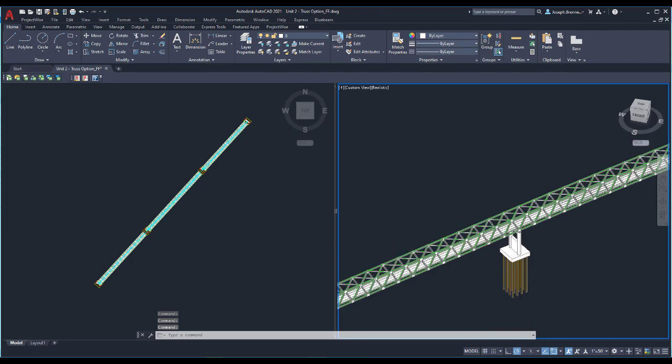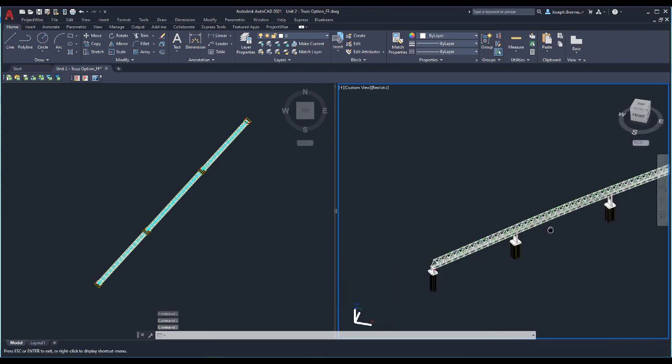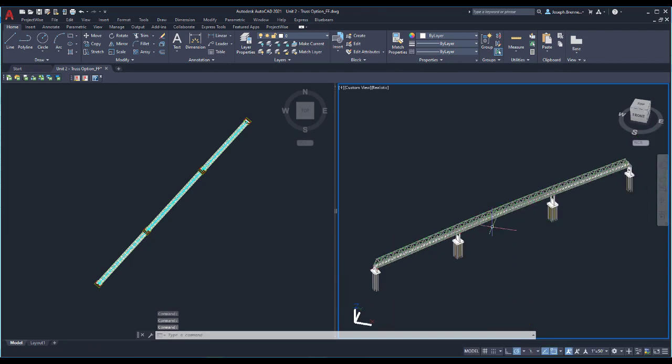We can build upon that and bring in our roadway corridors, any information we have. One thing I will say is that this is still an export process. I know there are some additional ways we can go through InfraWorks and then back out to Civil 3D, but in terms of direct from Revit to Civil 3D, the best process I've found is a direct export with DWG.